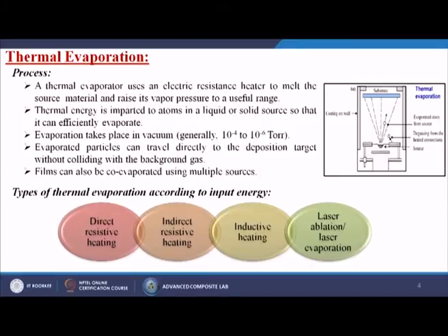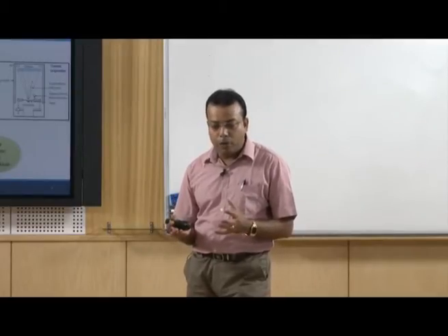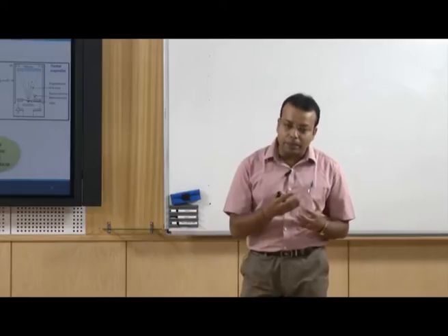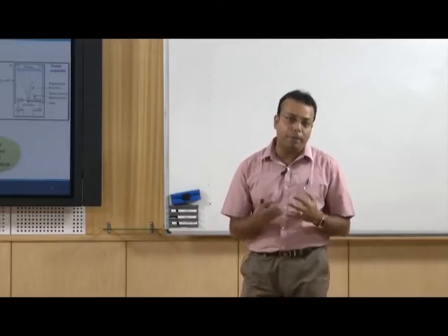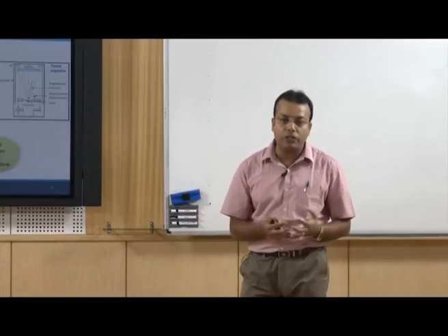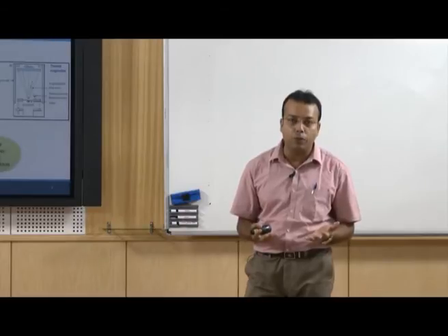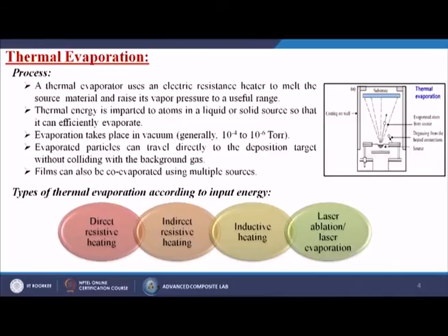Generally we are using a high vacuum, because otherwise, if we do not use the vacuum or certain kinds of inert gases, the vaporized materials can react with the environmental oxygen and maybe the moisture, and it can form new materials or some unuseful materials. Evaporated particles can travel directly to the deposition target without colliding with the background gas.